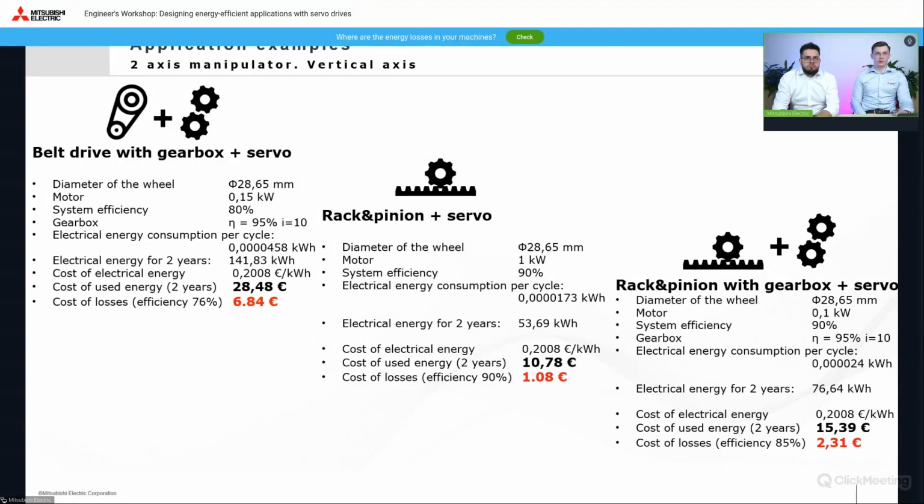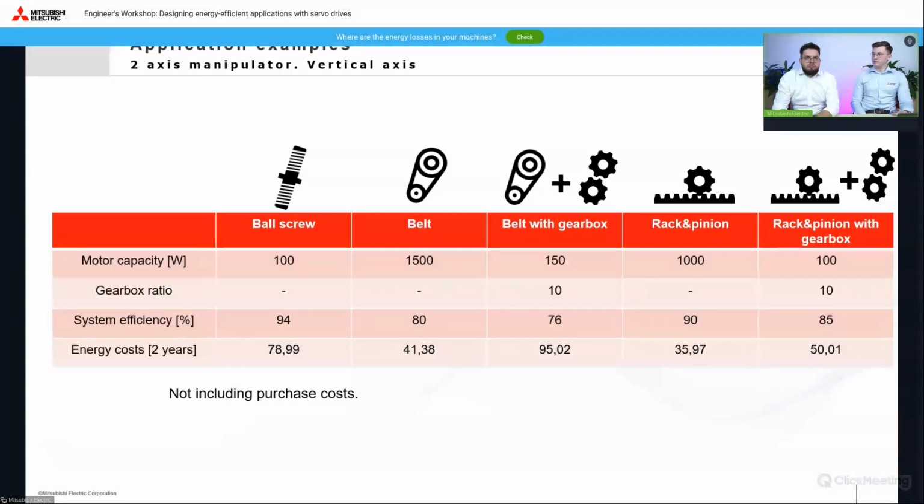So this is for these calculations. In summary, to do the same job, we can use different systems and, interestingly, different drive powers. A very important point here is that although at first glance a small geared motor would appear to consume less power, the opposite is true, mainly due to the internal resistance, which further increases our power consumption.